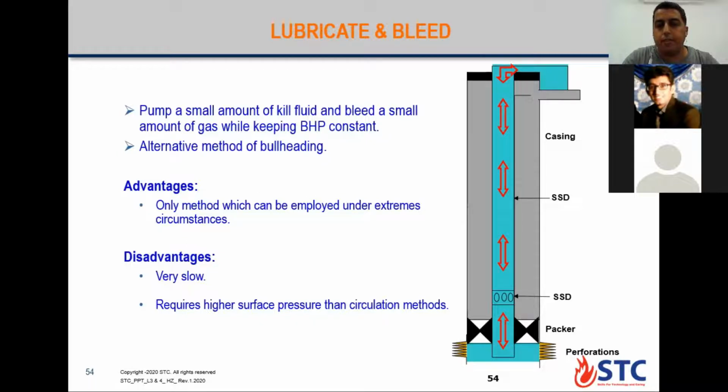First we will build pressure in the line above 2 to 3,000 psi, then open the well to pump the kill fluid inside. As we start pumping kill fluid, we would get more pressure at the pump. You're getting my point.